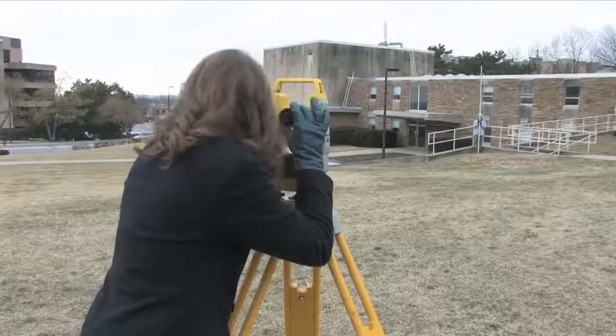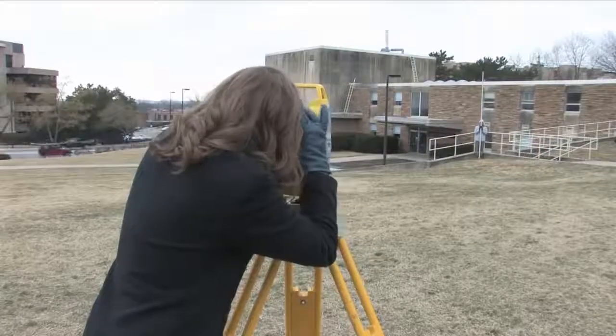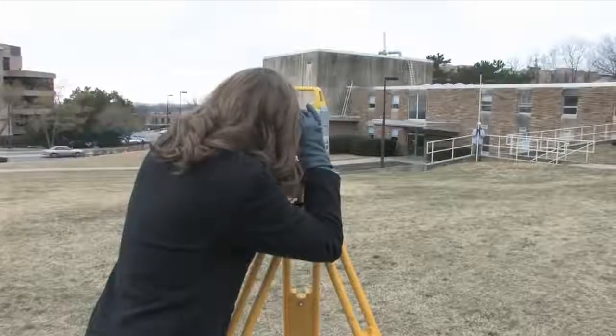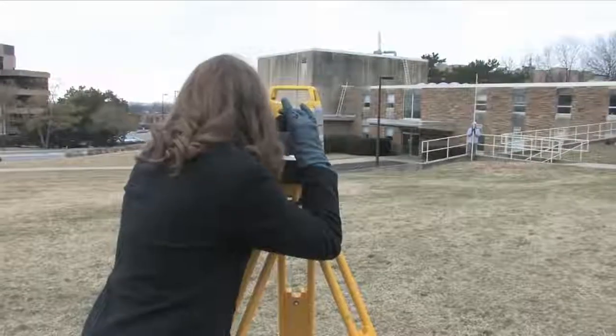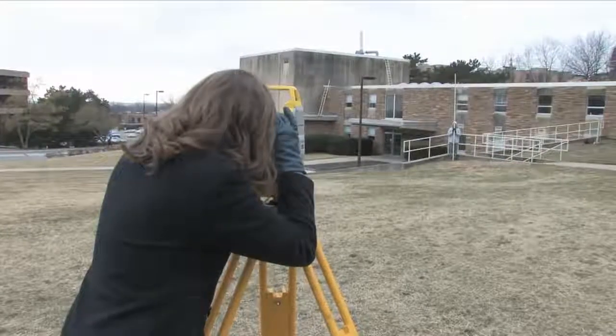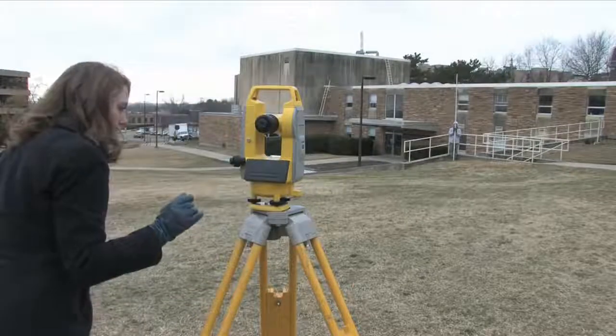Now proceed to rotate the horizontal and vertical angle locks, and then proceed to read the upper and lower stadia readings, as well as the vertical angle off the instrument, and record in the field book as a secondary measurement at point A. The objective now is to turn the angle to the right a second time.